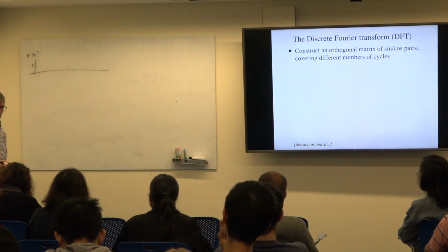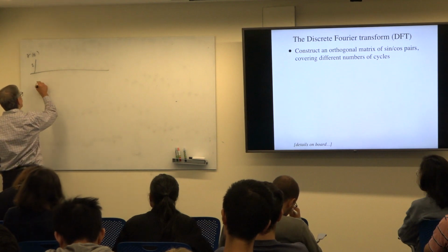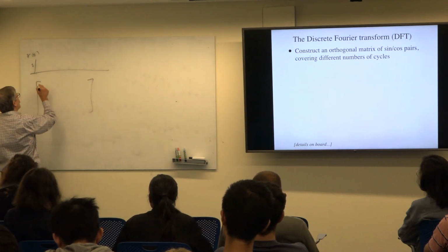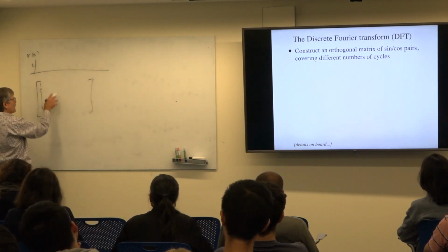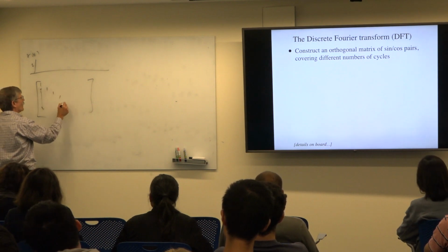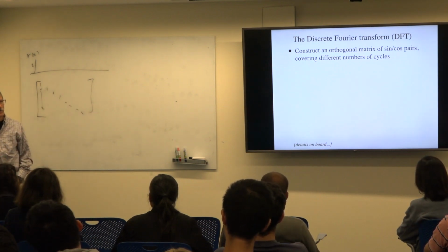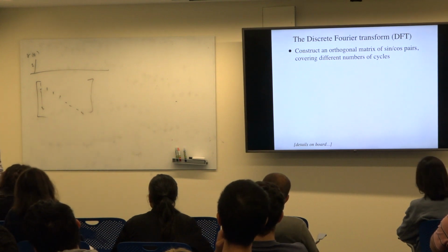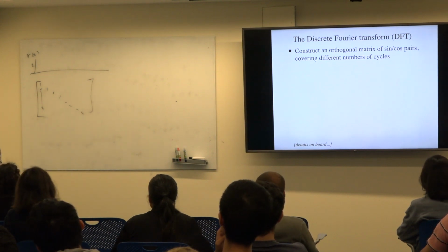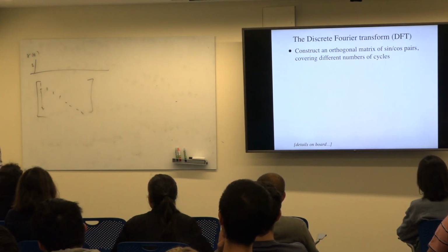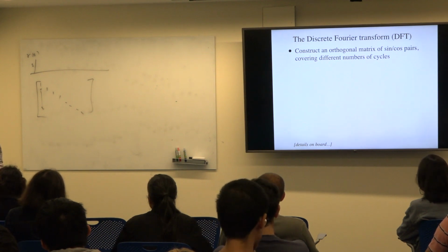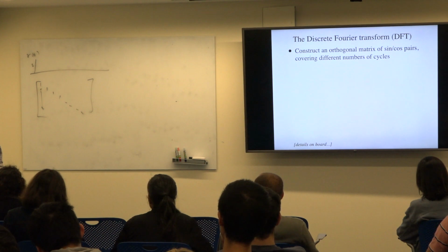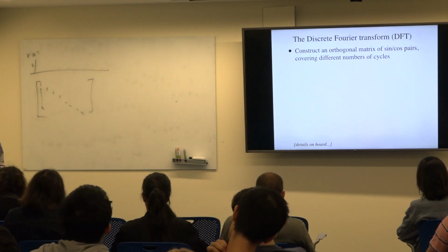We build our matrix. The matrix is built by shifting. So the impulse response is put here, 1 and a bunch of zeros, and then we shift it, 1, 1, 1. Okay? So what does that system do to the input? The output is related to the input how? It's an easy one, kids. Really easy one. What matrix did I just write down? The identity. This just copies the input to the output. Whatever the input is now gets copied to the output now, and that's all that happens.